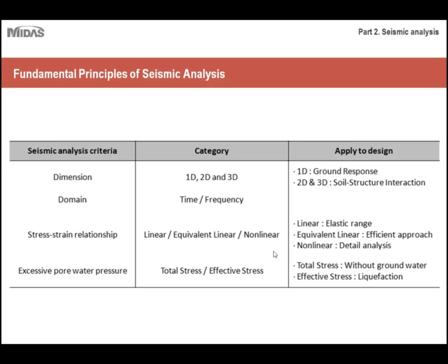But just keep in mind that when you have undrained soil conditions and seismic loading is applied to it, that creates a very dangerous and unpredictable environment for your structure. But for now, we'll just keep it simple, and we'll focus mainly on drained analysis. So the analysis procedures that we'll discuss will assume that the soil is drained, so without groundwater.